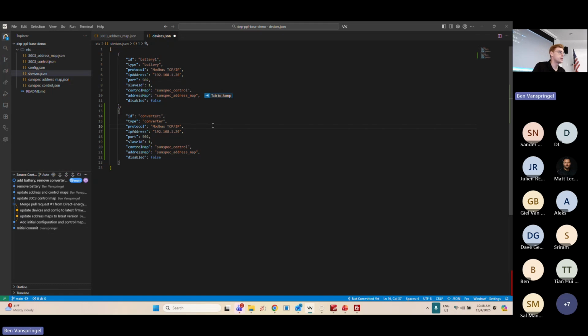This new device, this converter, will also be communicating to our controller over Modbus TCP/IP. So the controller, the battery, and the converter are all connected to the same network switch on the same network using Modbus TCP/IP. For the IP address, we'll type in another one. Our converter is at 192.168.1.21. For port, it's 502. Slave ID in this case is 240.